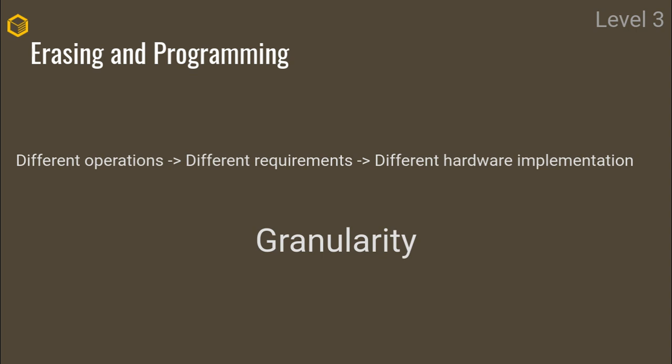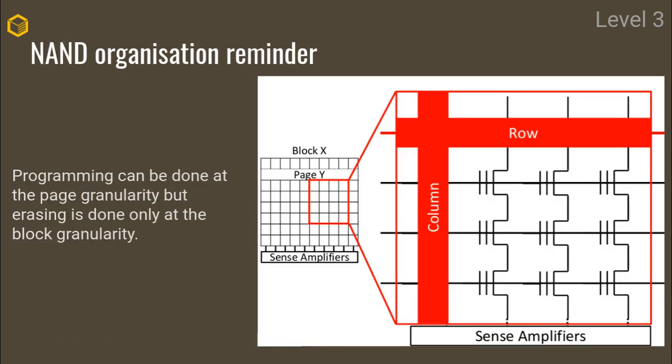In current implementations, what they actually do is that they build this to different granularities. So what do I mean by this? Well, the idea is that what actually happens in your SSD is that you can add charges at a page level, but if you actually want to erase charges, then you can only do it at a block level, for cost reasons.